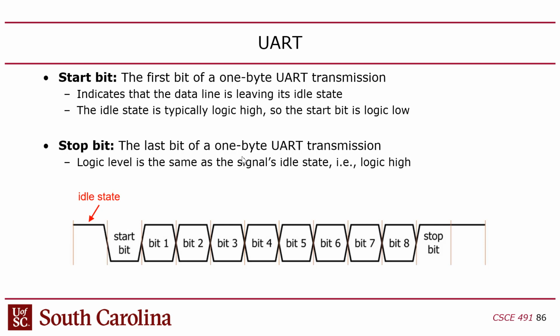They're unavoidable because there's no guarantee that you won't violate the setup and hold time on the receiver end. However, if we make the bit times ginormous by having a very low channel rate, the likelihood of that happening is kind of small. For example, if you tried this on SPI, it would be horrible because SPI is megabits per second. But if you try this at kilobits per second, yeah, you'll get some errors, but you probably won't notice. It'll just be a glitch here and there on your terminal, right? That's the thinking.